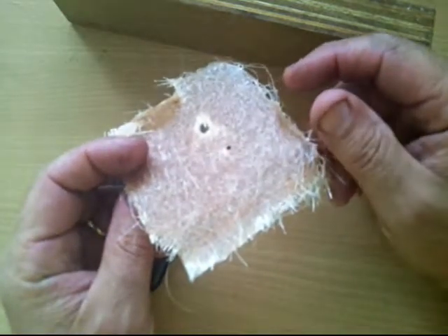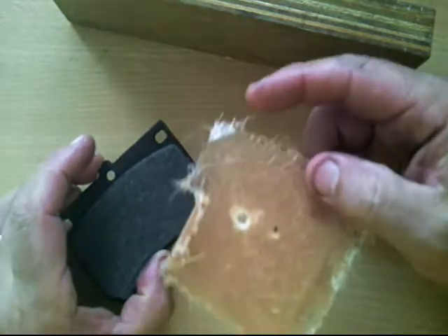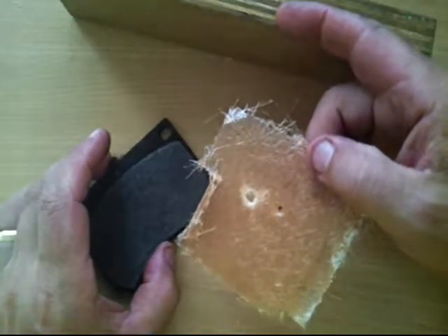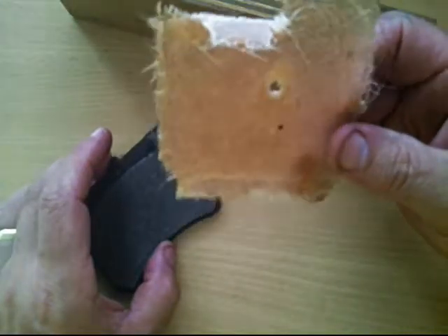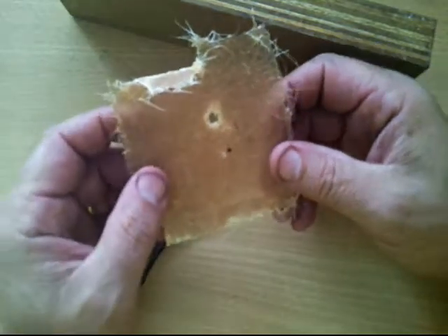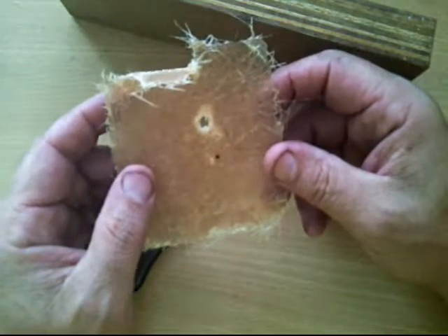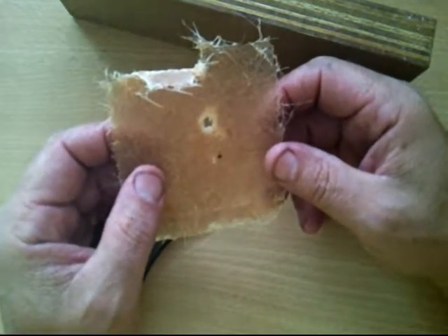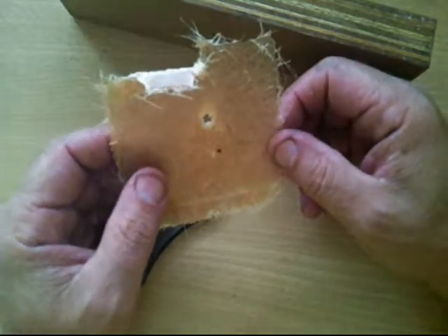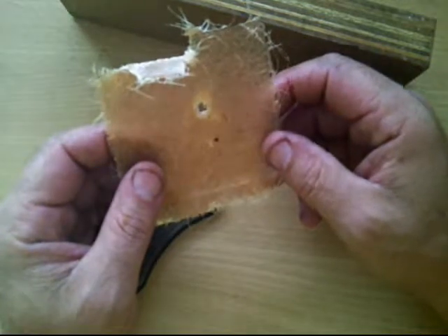So three different types: particulate, like that, small round particles. They can be laminar, like the plywood, or they can be fibrous, a fibre composite, like the fiberglass that I'm holding here. Now, while we're about this, composite material is usually made up of two different sections. They're made up of a matrix, which serves to hold parts together, and reinforcements, which provide desired surface properties of the composite material.